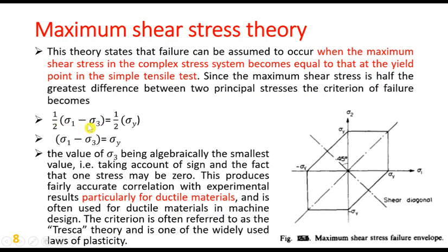We have covered this in previous lectures. This is tau max, the maximum shear stress, and this is the value of shear stress in the simple tensile test when the yield stress is reached.